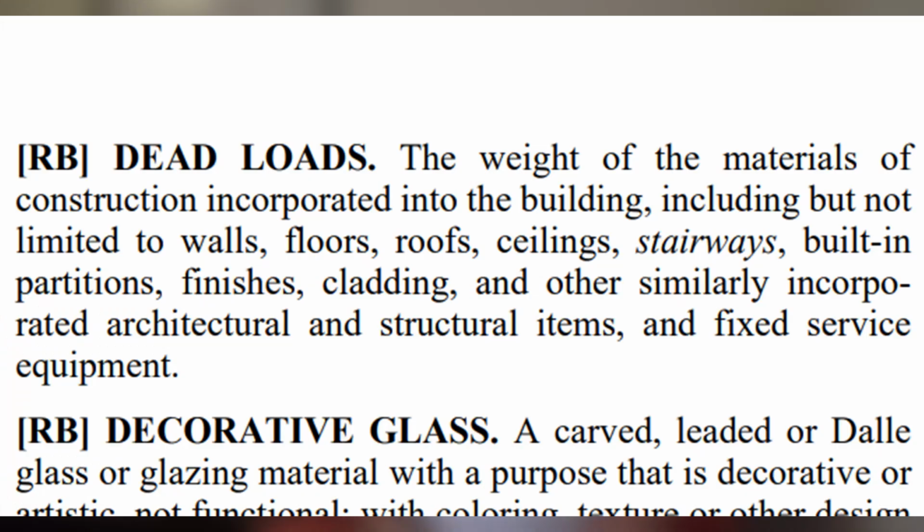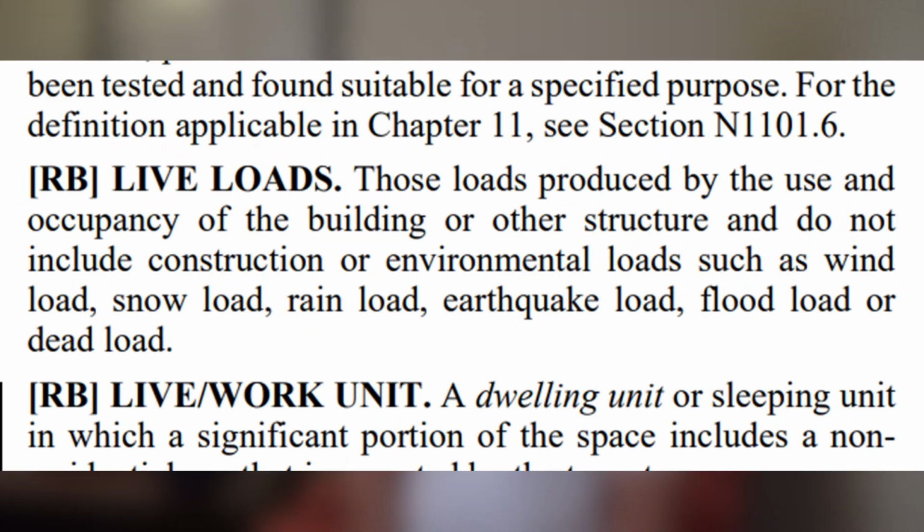Now here's how the International Residential Code defines them. Dead loads are the weight of the materials of construction incorporated into the building, including but not limited to walls, floors, roofs, ceilings, stairways, built-in partitions, finishes, cladding, and other similarly incorporated architectural and structural items, and fixed service equipment. Live loads are those produced by the use of the occupancy of the building or other structure and do not include construction or environmental loads such as wind, snow, rain, earthquake, flood, or dead loads.